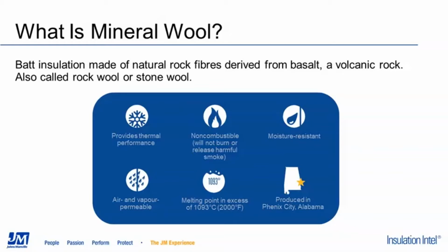So one of the advantages of working with a company like Johns Manville, which has a wide breadth of insulation products, is that we can be relatively agnostic about all of the materials. So while there's a lot of information out there that suggests MinWool is far superior from a sound transmission perspective, the reality and the science supports that the human ear really cannot detect the difference between the two. So when it comes down to it, MinWool is all about fire performance.